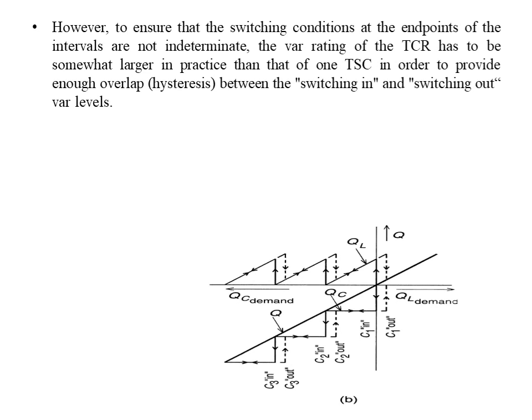Ideally, as I have said, the TCR absorbs the surplus capacitive VARs, so the rating of the TCR should be equal to that of the TSC. But practically, the rating of the TCR should be higher than that of the TSC.